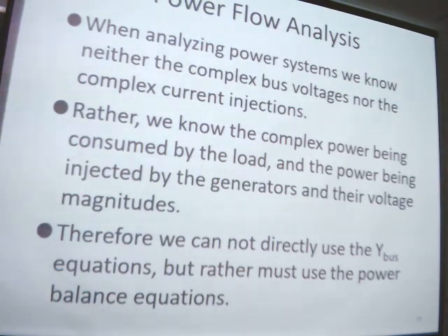And sometimes what we know is the complex power being consumed by the nodes, the power being injected by the generators, and the voltage magnitudes. Therefore, we will need some preparations before we start to use the Y matrix equations, okay?